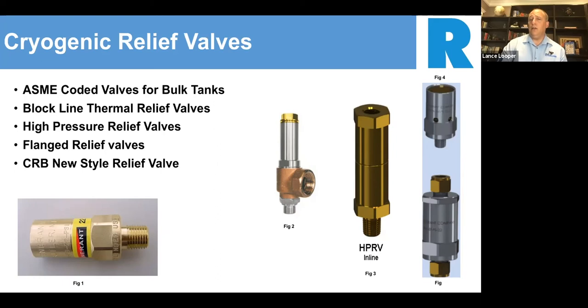It's on your liquid dewars, and it's a very unique relief valve because it actually acts more like a back pressure regulator. I'm just going to give you an example. If you are ever in the plant or at a customer's facility and you see these valves opening or starting to chirp on you a little bit, they're actually designed to do that. And they're not leaking. A lot of calls that I get are saying, hey, my relief valve is leaking. I hate to debunk that, but that's what they were designed to do.